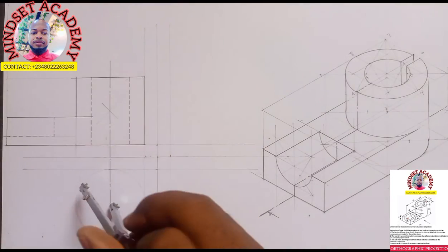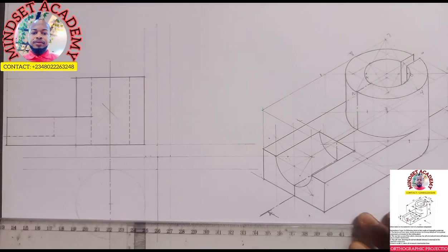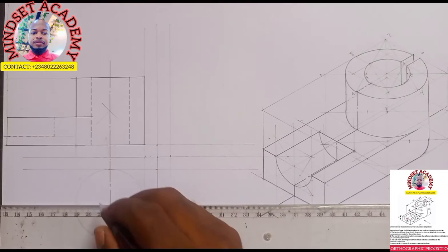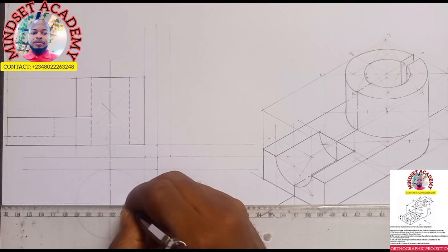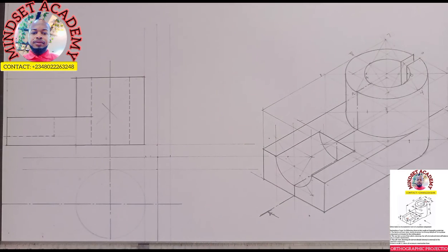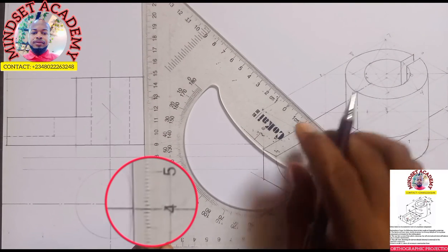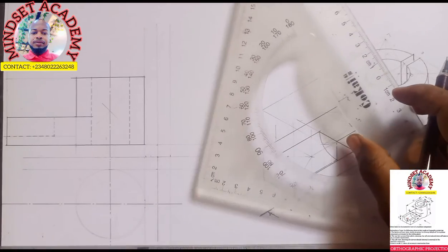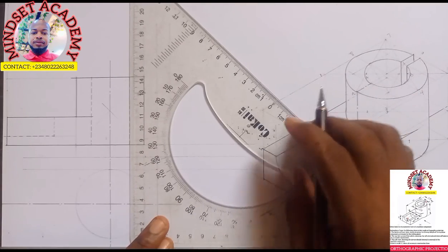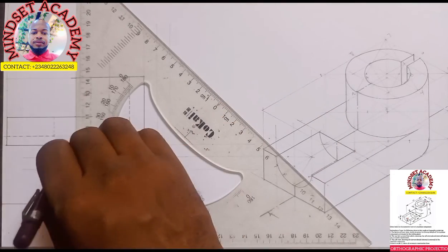And the question is, why am I using faint line? Because of these two thickness here, and that's giving us 6 millimeter, right? So just draw your center line here this way. Long, short, long, short, long. So let's measure the 6 millimeter here from zero. From zero, this is 0, 1, 2, 3 up, 0, 1, 2, 3 down. Can you see that? So when I now come down, you just only need one part here. This will give me this, just like this is giving me this.